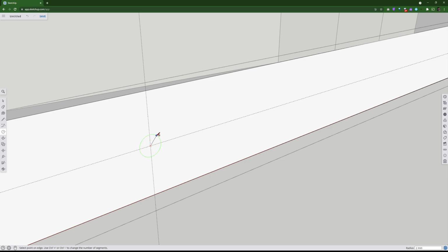Okay, I'm going to draw a circle. Now it wants the radius there. I don't know if control, there is a way to change the diameter, but I know what diameters are. I'm going to drill that out with a 7 mil diameter drill bit, which means the radius would be half of that, 3.5. And I'm going to keep it like, because SketchUp doesn't do real circles, it does kind of these funny polygons, just so it works quick and does the math quick, geometry. I'm going to make it 3.5.